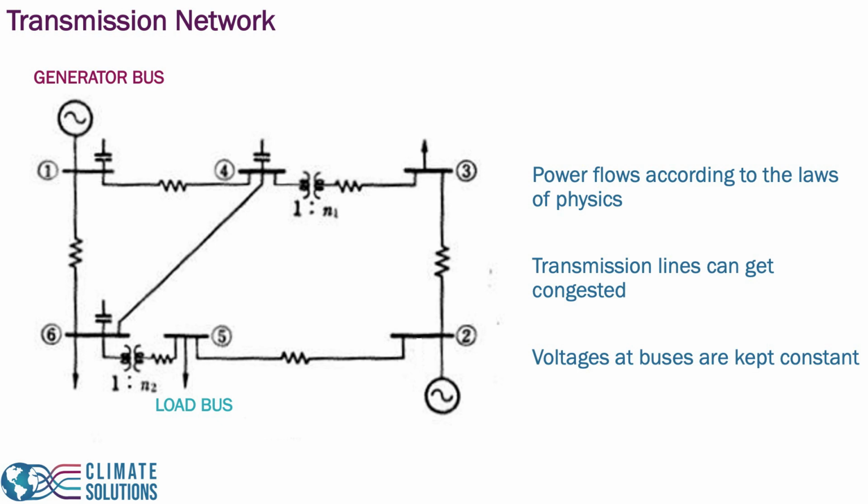At every node in the power network, or bus, we can measure a voltage signal that is sinusoidal. The frequency of this sinusoid is set to be close to 60 Hz in the US grid. The voltage signal has a magnitude that relates to the peak value of the sine wave, and a phase angle that measures the shift of the sine wave at each node with respect to a reference node.